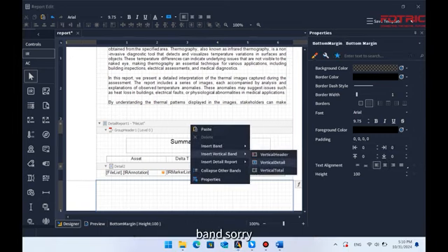Now that your table has been created, you can add the different bookmarks or pull the information from the IR image into your report template. There are different ways you can do that by simply clicking on the cell, clicking on the formula, and then go find the specific values that you want to add. Let's say you go here to IR marker list and then select, let's say, maximum temperature, double click, and then the software will create the code for you, basically. Now you can explore there and I invite you to do it. You can also go to user manual and support, but for this video we just want to keep it short.